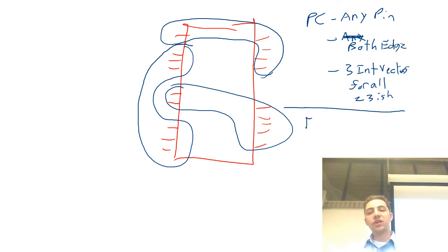Contrast that to external. Only happens on two pins, and I think they're about there. Okay, D2 and D3. They can be level triggered, low level, any edge, or rising or falling.